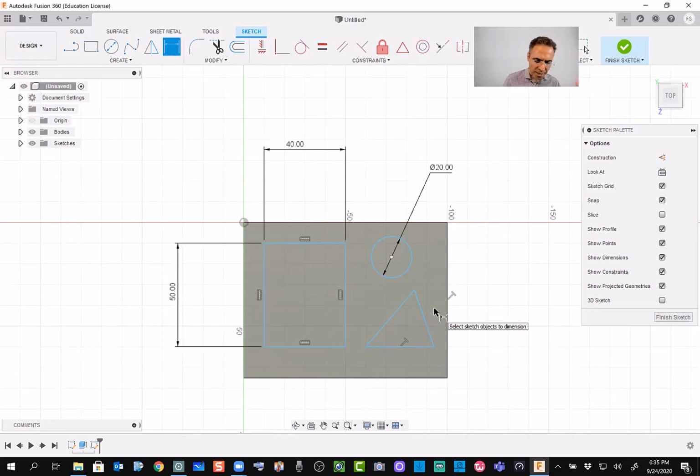And the same for the triangle, you can change the angle. For example, here, what do you want the angle to be? So this is not a nice angle. Let's change it to 110. You got the idea, right? And let's say the position of these things, you select the center, you select this edge, and this distance, you want to set it to maybe 20. Something like that, all right?